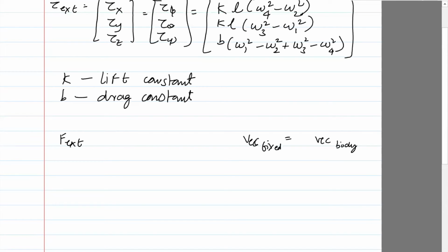In order to find the relation between body frame and fixed frame, we rotated by the rotation matrix R, right? Because in this case, we are trying to express the force from one frame to another. The force Fz really depends. The force basically is acting along the z always, but as the quadcopter tilts, it's going to have a different effect than when the quadcopter is perfectly aligned with Fz. So what I need to do here is write R times the thrust minus, I'm actually including another force called drag force, which I've not written down so far.